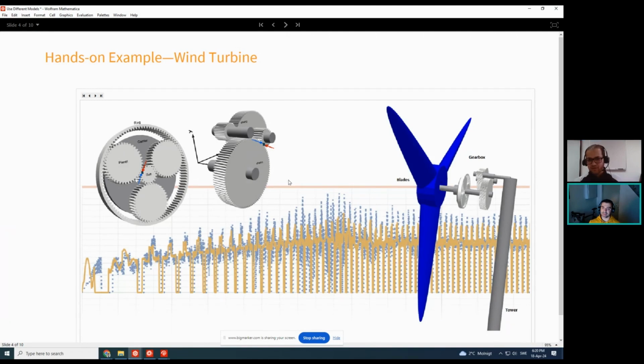So what I see is my blade is attached to the sun wheel, which is in the center. No, actually, the carrier. The carrier over there, the plate behind it. Exactly. And then that rotates, and because of the interaction between the ring, carrier, and those planet gears, we are seeing that they can also rotate around the carrier and around their own axis.